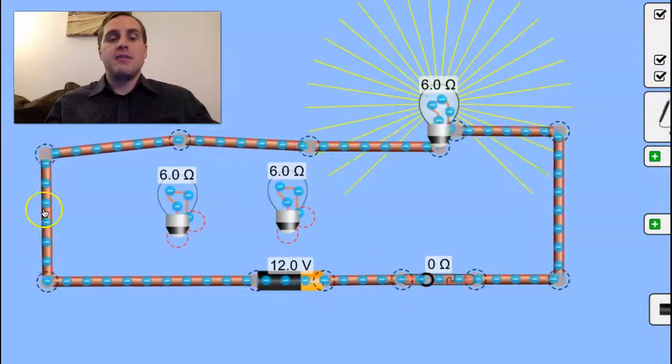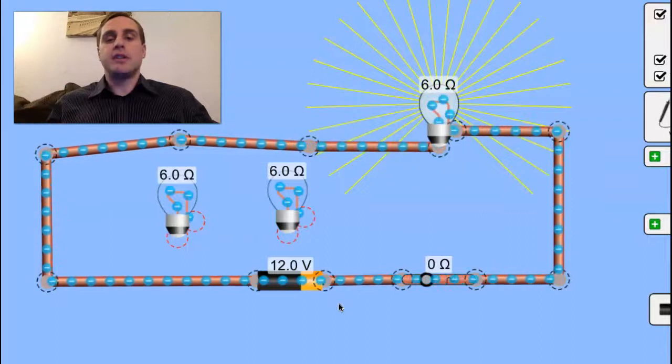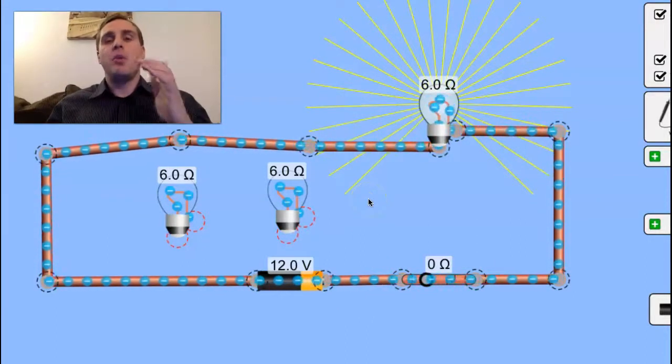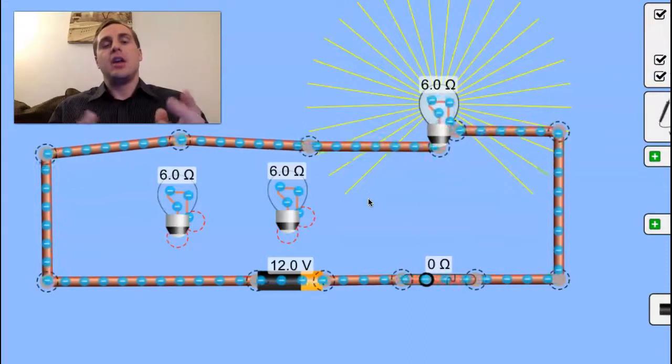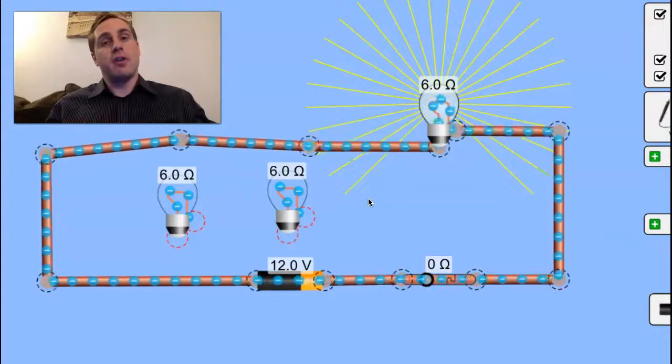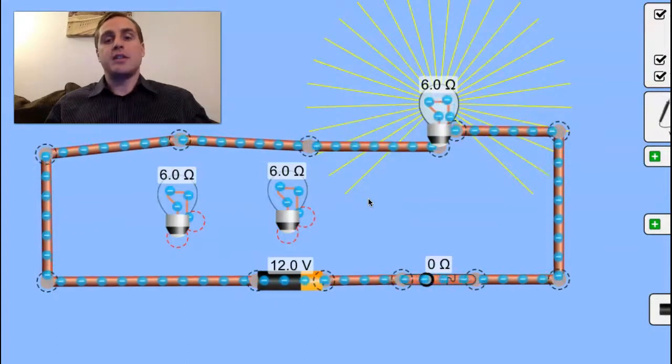In fact, for the sake of this course and for most basic electric calculations, wires are assumed to have zero electrical resistance. Now, zero electrical resistance is not a perfect assumption, but even most modern wires have very small amounts of electrical resistance, if not over a very large distance. In other words, only when we transmit electricity over very large distances, like electrical transmission power lines and very long wires, is there power loss due to the length that we transmit the electricity over. So it's not a perfect assumption to assume that wires are without resistance, but it's a good enough assumption for our purposes.